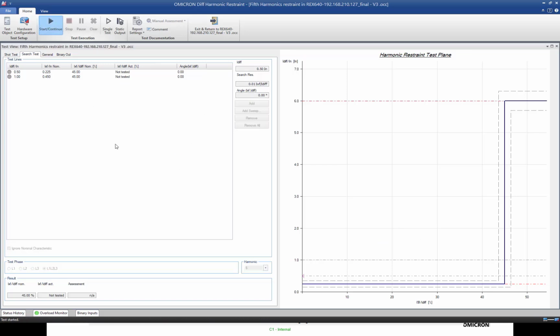Now the CMC will superimpose a waveform at 300 hertz if you are using a 60 hertz power system, since fifth harmonic means 300 hertz. But for our case in Bahrain, the nominal frequency is 50. So now we are superimposing a second waveform with a frequency of 250 hertz on the fundamental waveform, without any rewiring, without any reconnection. You just have to select the values, and it will be implemented from the CMC to the machine directly.